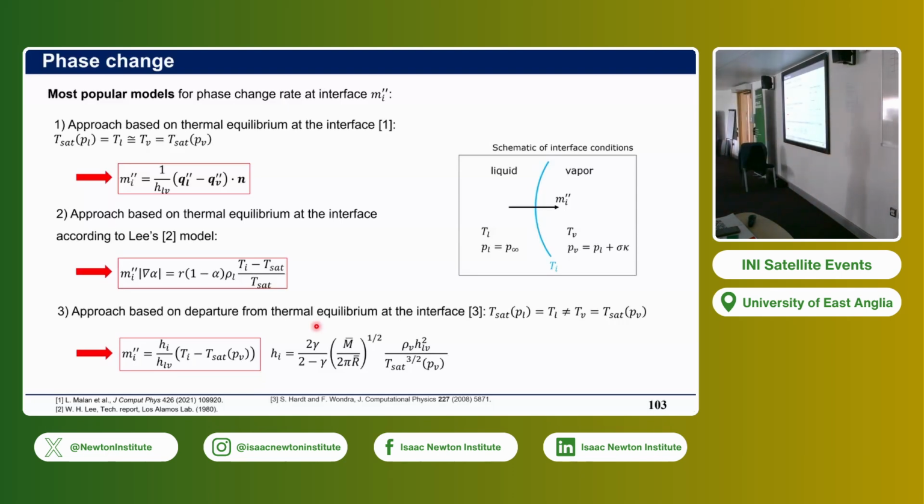Yeah, but it seems that in this model, you assume that the velocity of vapor and the velocity of air are the same. But actually... You're right. If you look at the kettle boiling, we can see vapor going up, and the air actually going down. So there should be a so-called two-velocity model. Could be done, yeah. Is it possible? I think it's possible. It's not that simple, because everything needs to be coupled also with the liquid. Let's say that this works fine as long as they share the same velocity field.